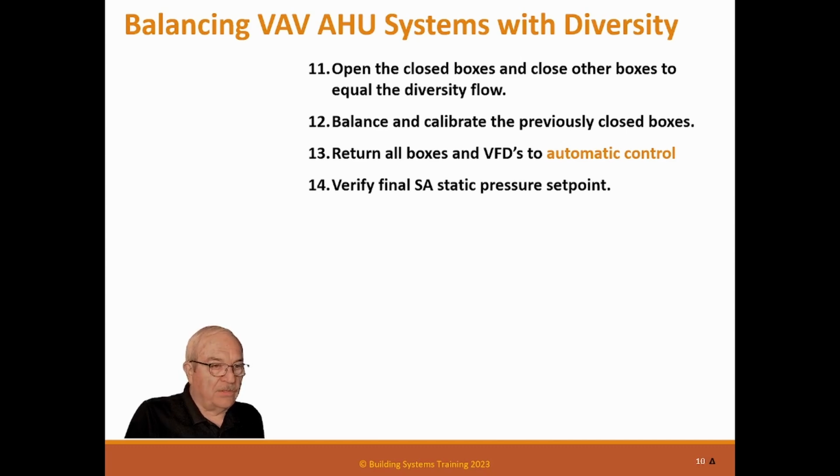It's not difficult, but where people get messed up is they try to leave the air handler in automatic static pressure control. That will not work, because it will vary, and that's not what we're trying to do. We're trying to guarantee that the design CFM of the air handler will provide designed air at all the boxes at the same time. That's our maximum flow deal. And if you leave it in automatic, it won't work. You can't do that. So that's where people get messed up trying to figure that out, and that just won't work.